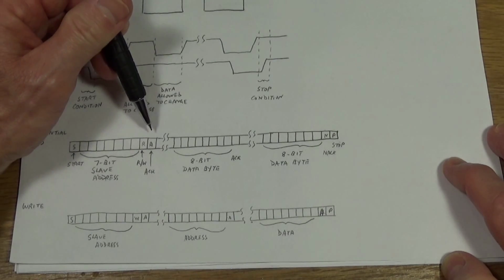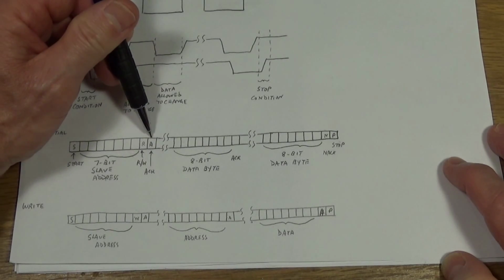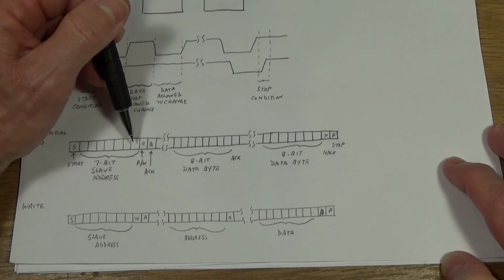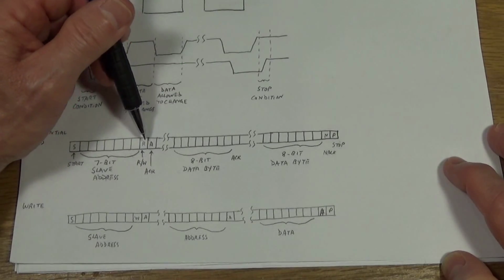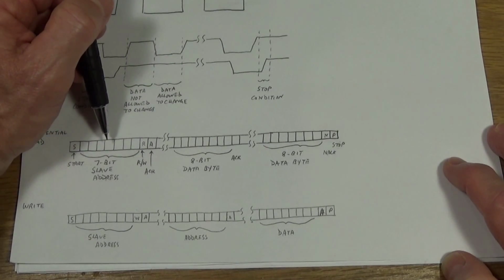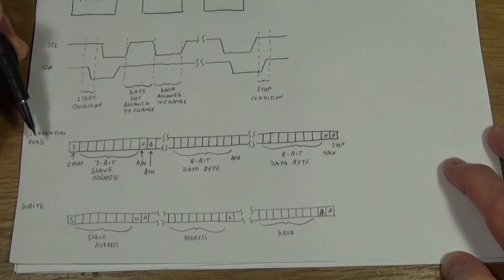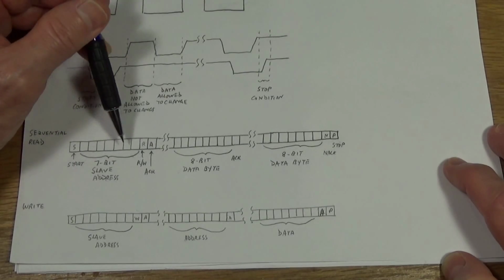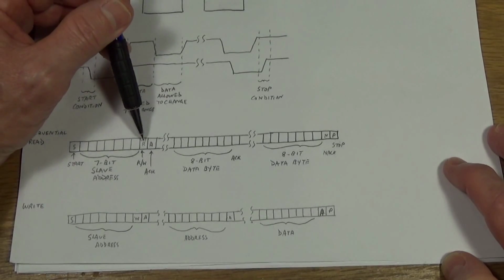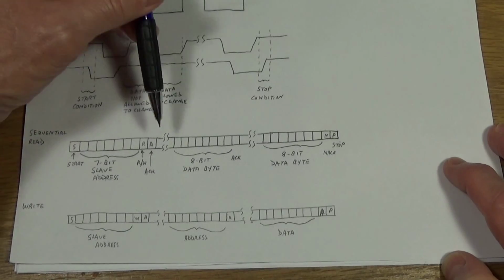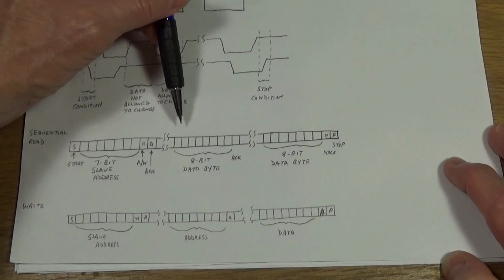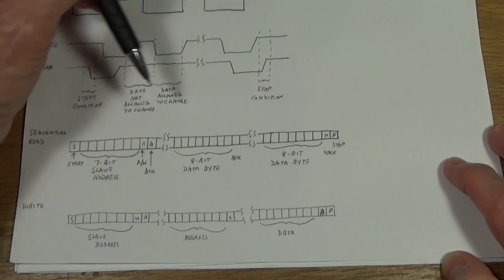It then clocks out one more clock, and the slave that has that address acknowledges by pulling the data line low in this clock cycle here, and that just tells the master that somebody is out there and is ready to communicate. So in a sequential read here, the master clocks out the 7-bit address, followed by the read bit. The read-write bit being high indicates to the slave that it wants to read from it. The slave acknowledges, and then the master starts issuing clock pulses for as long as it wants to read bytes